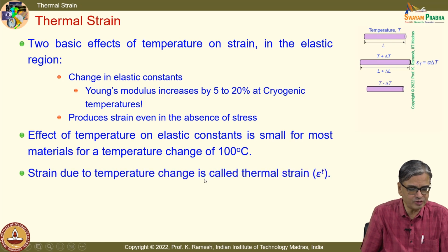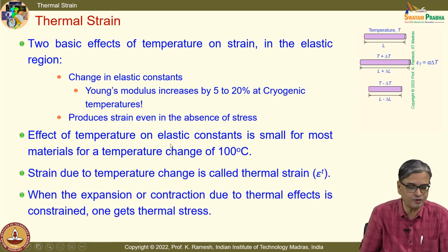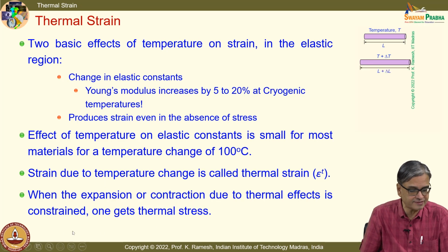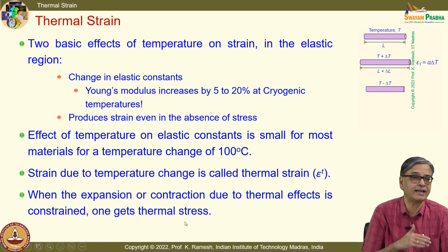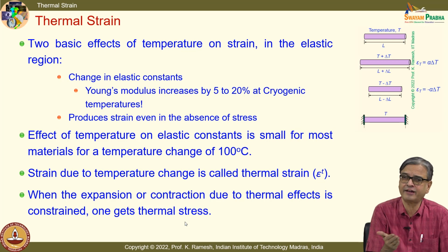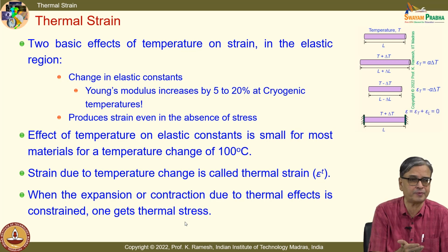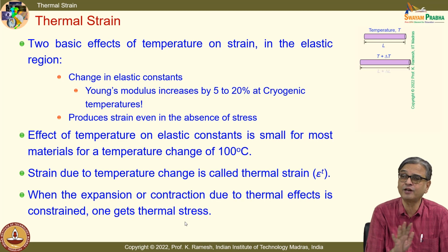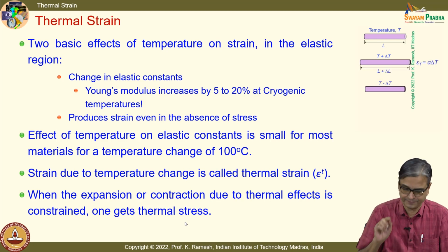And this is also stated when you are talking about changes of 100 degrees centigrade, do not worry about change in elastic constants. And as I mentioned earlier, anything related to temperature, you call that a thermal strain. When the expansion or contraction due to thermal effects is constrained, one gets, in addition to thermal strain, thermal stress also. You have the strain relation. The strain relation takes care of that. It has stress components as well as a term related to temperature. So, if you use the expressions properly, you can find out the thermal stresses and thermal strain comfortably.